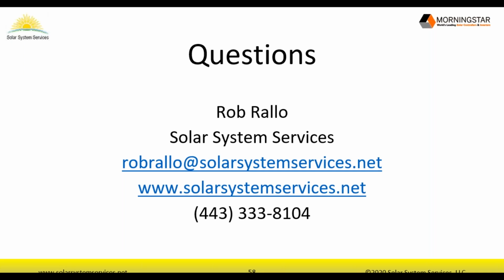Let's see, I had a question on, can we use lithium batteries with the ProStar? One of the advanced features that was covered in the presentation that Rob was talking about is a setting called lithium foldback, which not only allows the preset to be loaded into the product with our ESP program, but you can also set current limiting at low temperatures so that you're not charging lithium batteries below a certain point, which is really what they require for the specs.